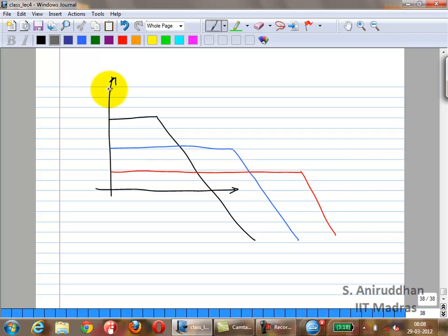So let us say this was a dominant pole. Oops, sorry. In this particular case it comes here. I'll get a second pole here. And then somewhere here I'll get a third pole. It should go down. Right? Is this stable or not? As I've drawn it? It's stable. And it's probably going to have phase margin slightly larger than 45 degrees. I can also say that.